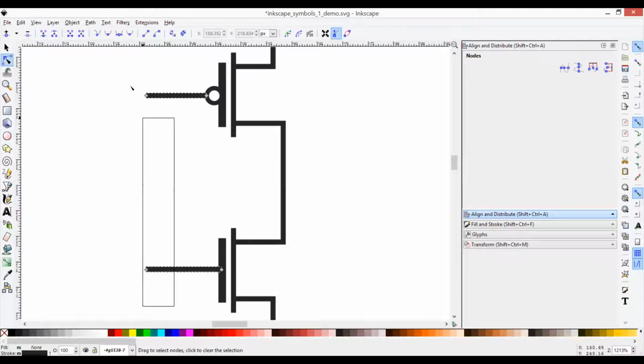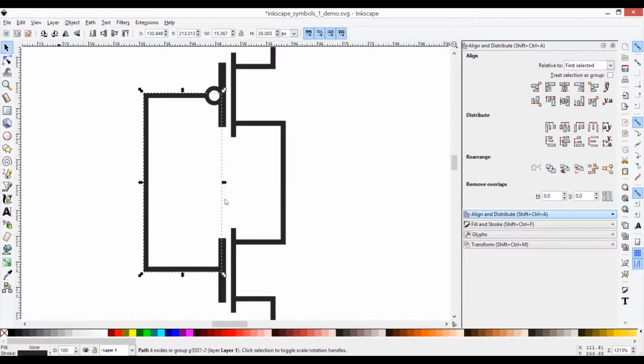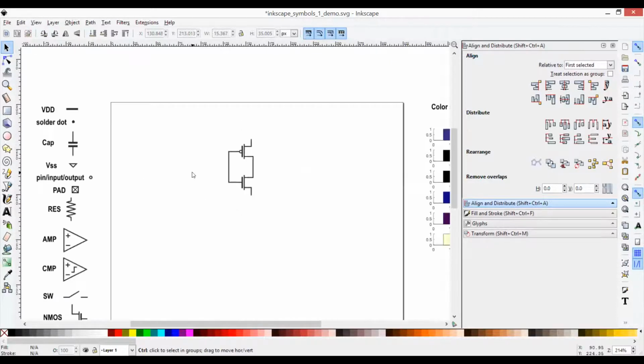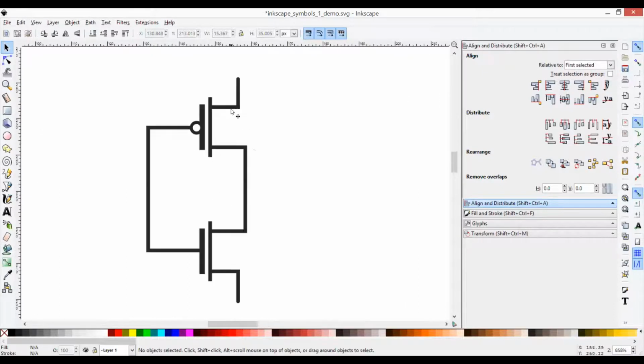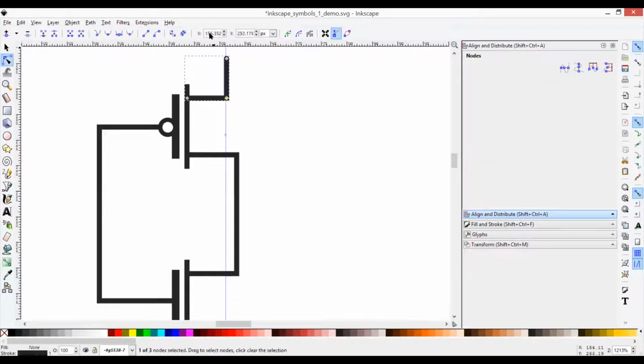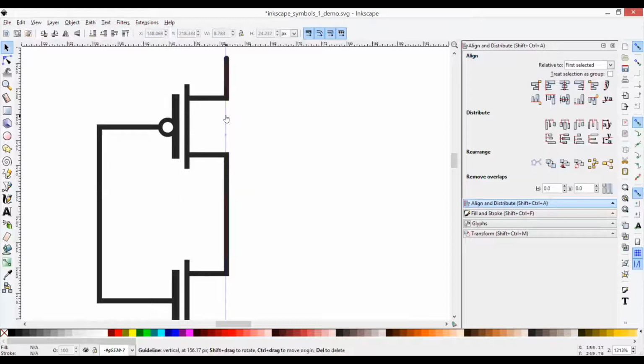And this is basically how I make the schematics. Once I've got all my pieces put down, this is how I draw the lines between transistors and stuff. You can see that this is not aligned anymore. And you could create a rule by clicking over here and dragging out to see alignment. So obviously this wire here is too far out. So I can click on this, highlight the X coordinate and copy it, and then go to these ones, highlight both of them and paste the X coordinate, and now it's perfectly aligned. And then I can hover over this ruler, this line, and then press the delete key and it'll go away.